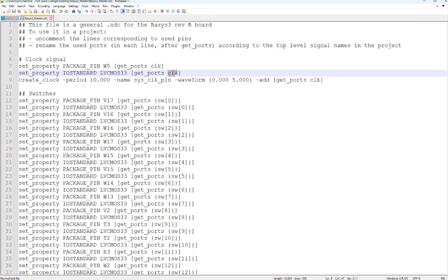If you use this wire here, it's actually being used as a port of the top. So clock has to be lowercase CLK, and that's a 100 megahertz pin. It's a physical pin on the FPGA. You don't have to really spot it on the board. It must be somewhere. It's a very thin wire connected to the crystal, but it's definitely creating 100 megahertz, and you know this is existing somewhere on the board.